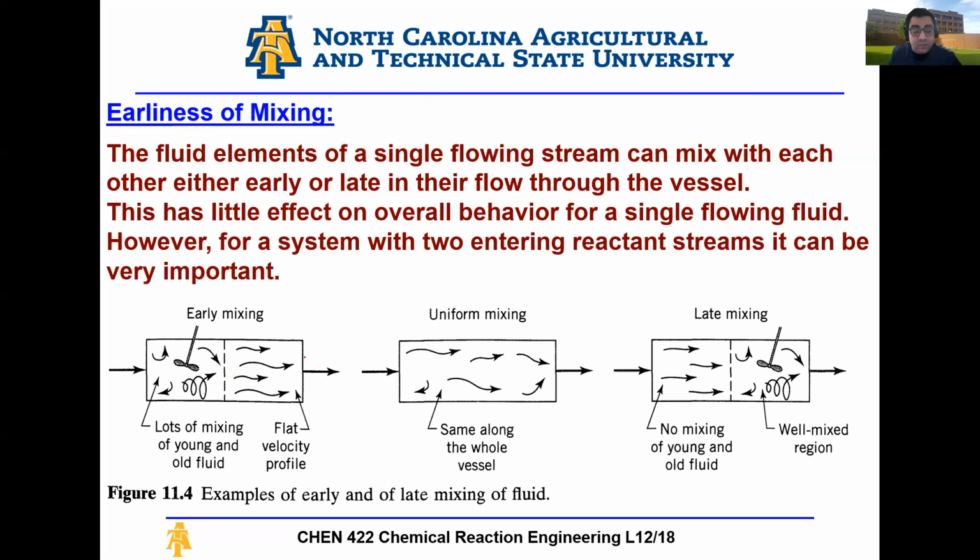If I compare this to an application in industry, this could be equivalent to a system full of liquid where I'm bubbling gas from the bottom through it. I'm getting some liquid product at the top, or maybe gas product. As I'm bubbling gas, I have a lot of mixing at this early stage, and then I have less mixing at this later stage, right? So I have early mixing at the first part of the reactor, less mixing at the second part of the reactor.